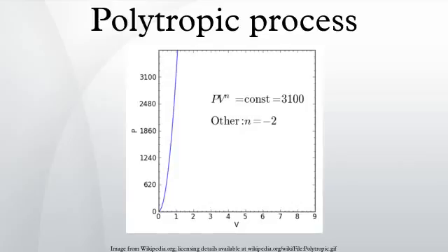Applicability. The polytropic process equation is usually applicable for reversible or irreversible processes of ideal or near-ideal gases involving heat transfer and/or work interactions when the energy transfer ratio Q/W is constant for the process. The equation may not be applicable for processes in an open system if the kinetic energy is significant. The polytropic process equation may also be applicable in some cases to processes involving liquids, or even solids.